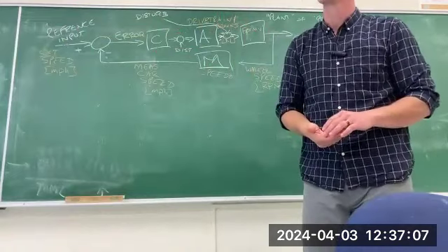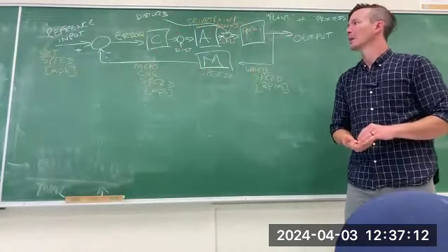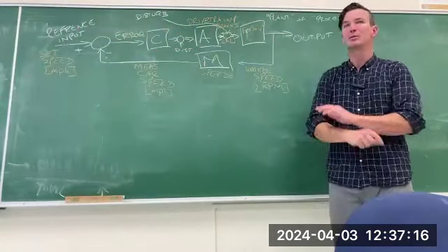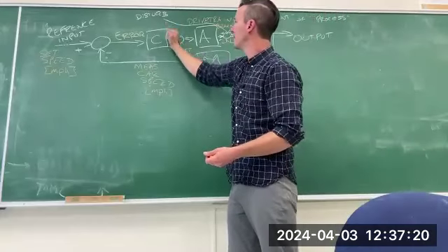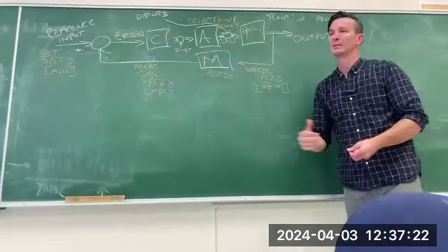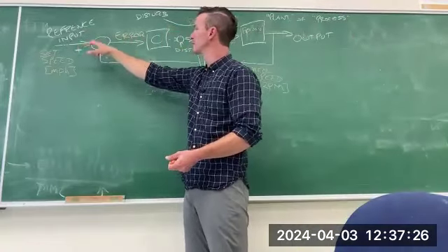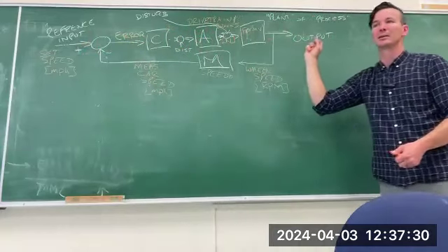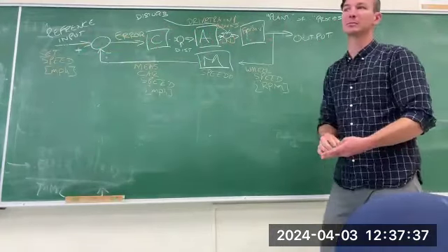Where would that fall? Tapping the brake? Sorry, yeah. I mean, that would basically eliminate all of this, right? If you turn the control system off, then you would be breaking that link. The speedometer is still going to be measuring. You might have still stored a reference, but whatever the controller decides doesn't get sent to the actuator. The actuator, the brake pedal, respects your foot above and beyond whatever the control system tells it to do.